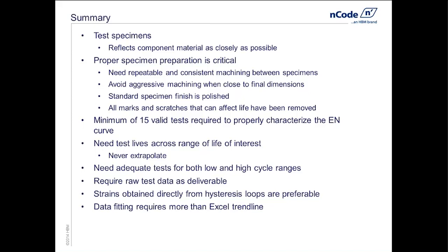One thing, if you're having this test done outside at a lab, you want to require that you get access to the raw data. For each test, you want as much data as they've computed. At the minimum, that would be stress, total strain, and life.